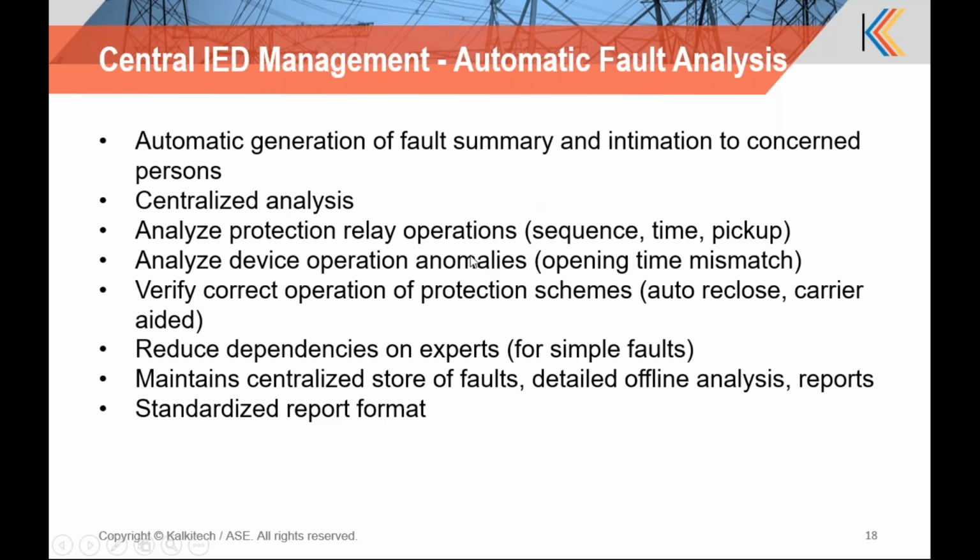Protection relay operation, its sequence, time and pickup need to be analyzed. Device operation anomalies, like operating time mismatches, need to be analyzed. Correct operation of protection schemes like auto reclosure and carrier aided schemes also need to be analyzed.